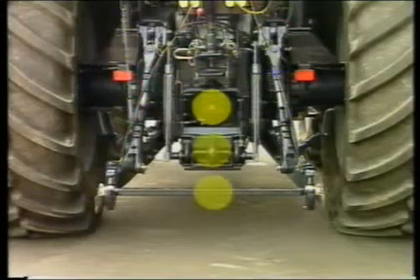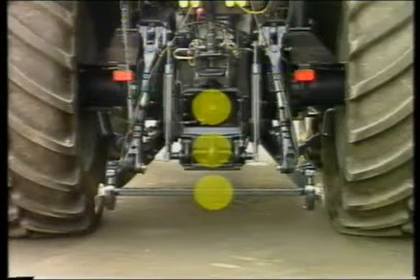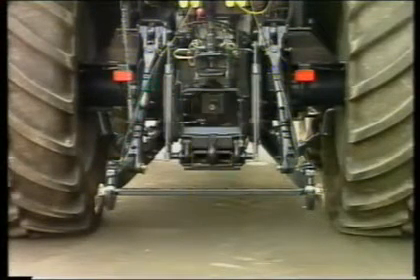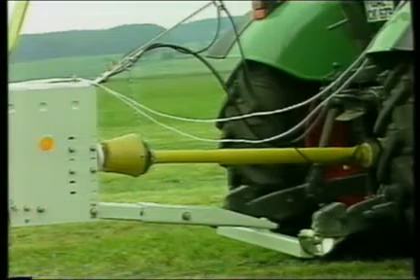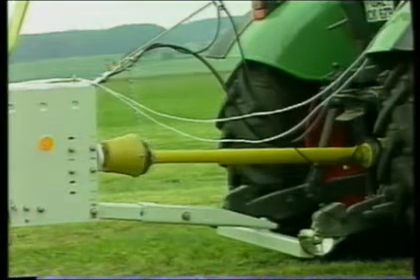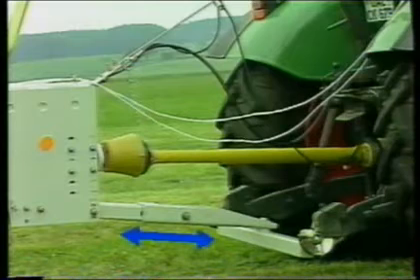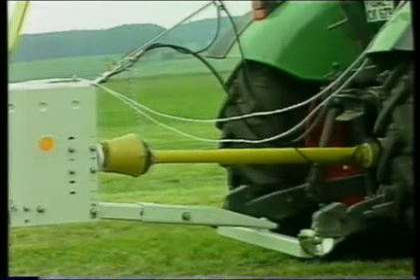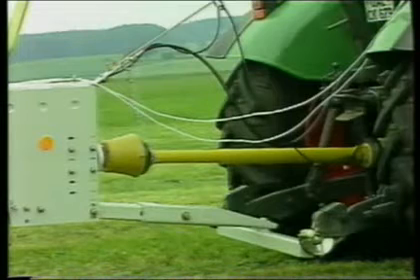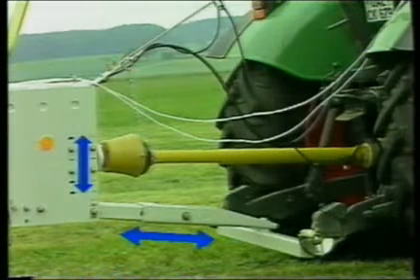The wide-angle constant velocity joint is a centered double joint. As with the W bend, the center lines of the PTO and PIC yokes intersect exactly between the joints. The centering system divides the total working angle evenly. Thus, uniform rotary motion is always guaranteed.